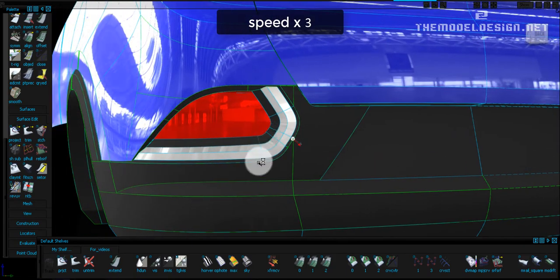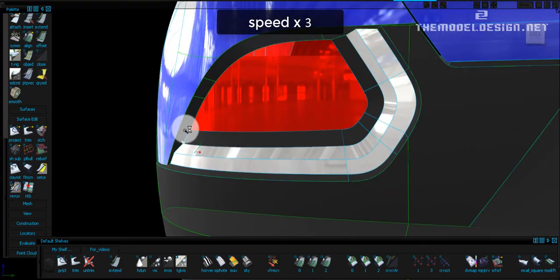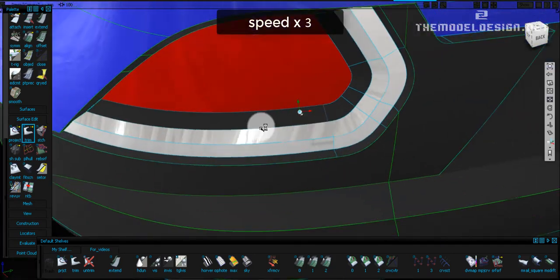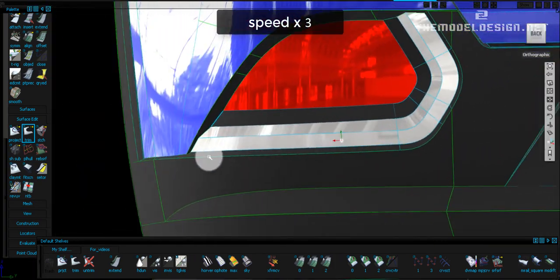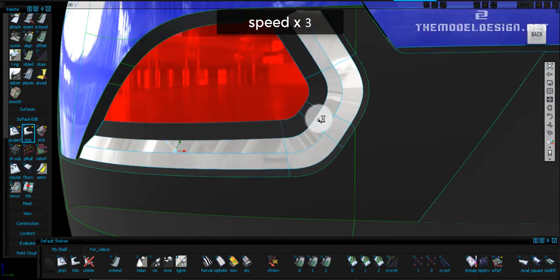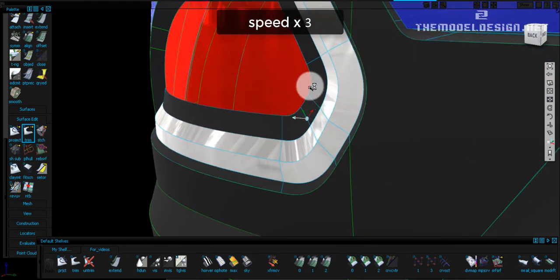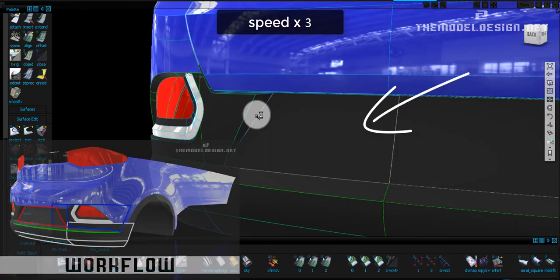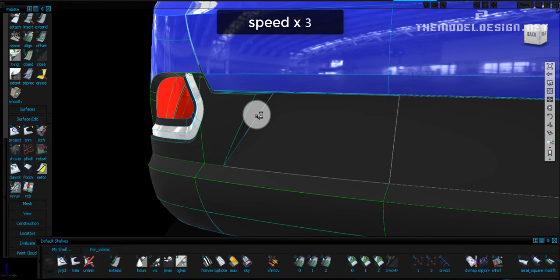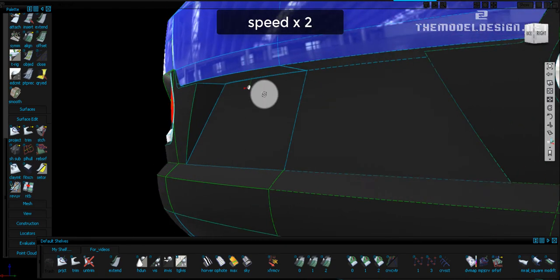Because we had a good G2 and almost G3 in here, we obtained a good looking organic form. There is no visible dips or bulges. Volumes and highlights are also good. There is no wobbling, no inconsistency. At last I created the number plate surface, but I didn't record it because it was simply just a matter of building almost a planar surface with little crown and minimum curvature.